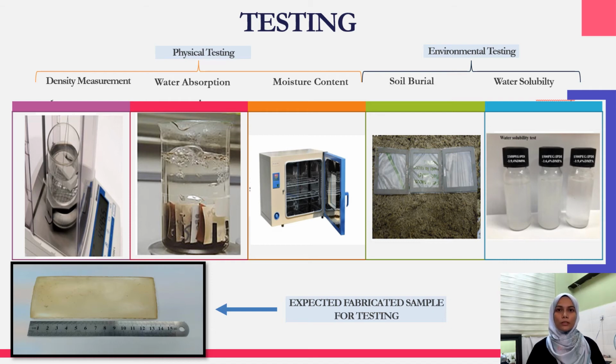And then for the soil burial testing, the sample firstly must be weighed and dried for 24 hours, and then it will be buried in the compost soil at 2 to 4 weeks intervals. And then after that, we will see whether the sample has completely undergone the biodegradation process or not.